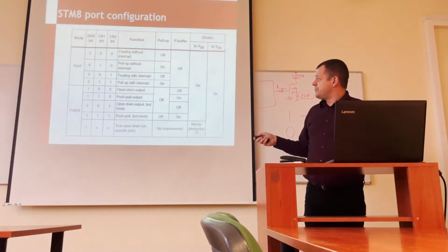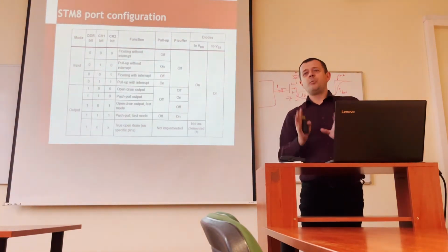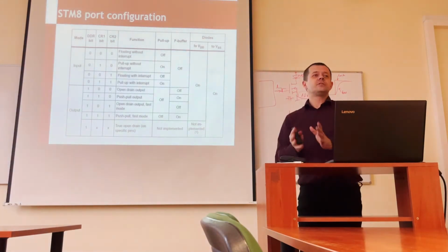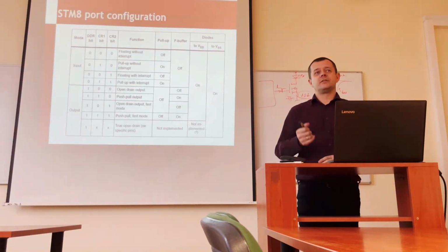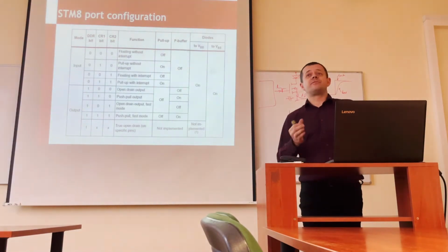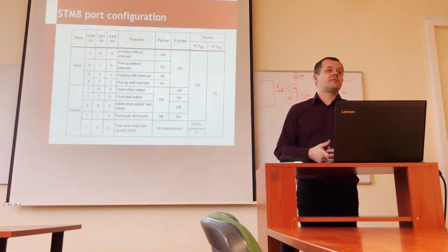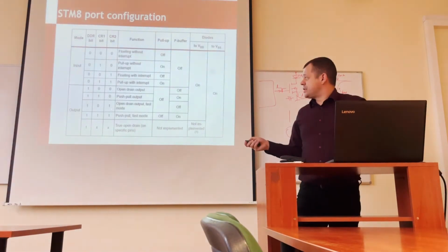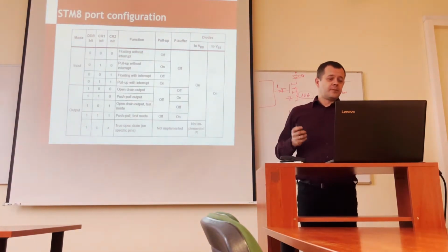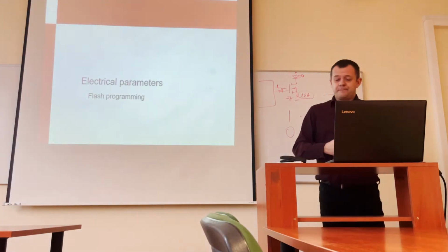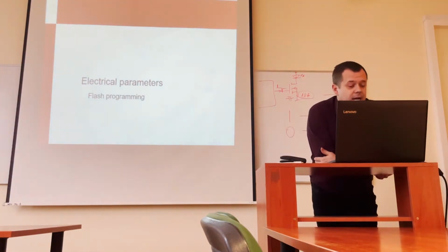If you want open drain functionality, don't count on megahertz. 100 to 500 kilohertz in open drain is a really good speed. If you want to switch at megahertz, use push-pull, because open drain is really sensitive to the pull-up resistance. We don't have time for it. Again, if you have any questions about this, I'm open.